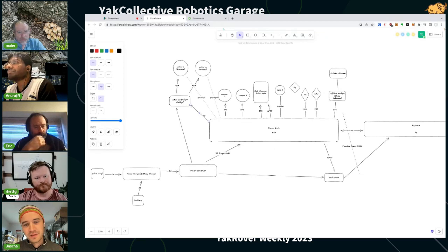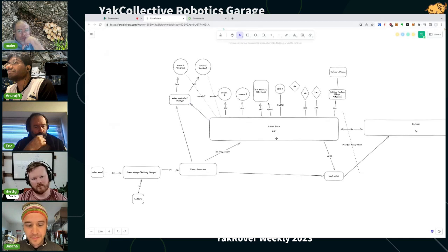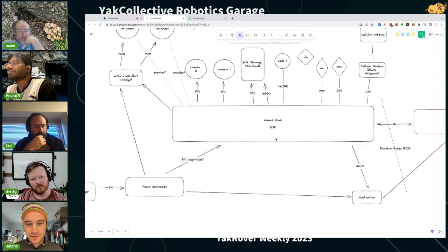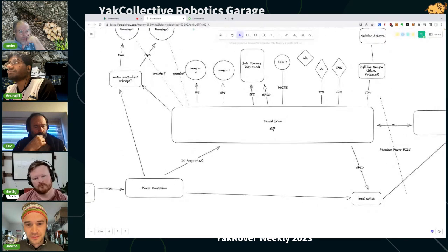That said, especially in a design like this, we might even have this issue already where we have a pin shortage. So we might have to put an IO expander in the design, or a MUX or some other component to give us more pins. Right. But if we don't want to use a pin expander, we could use a different chip.